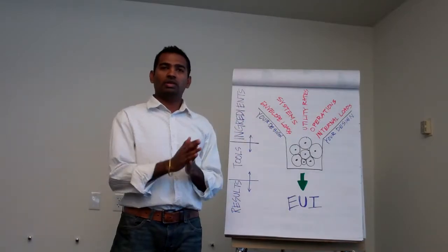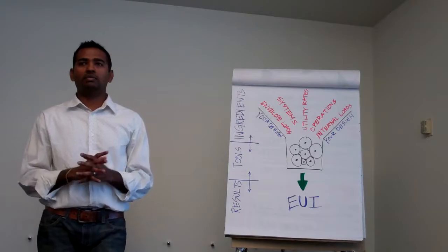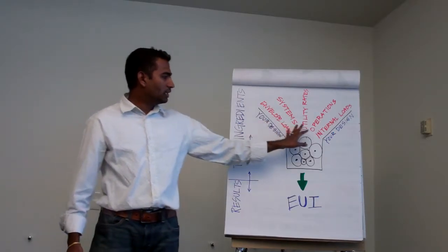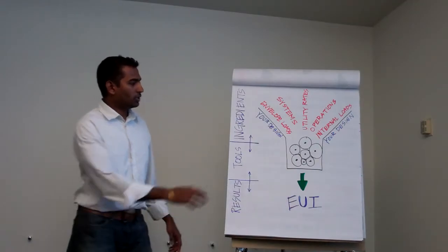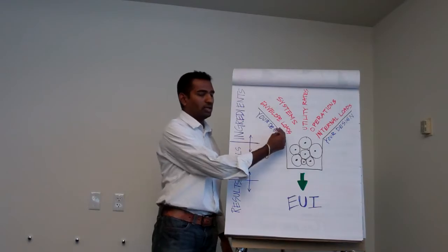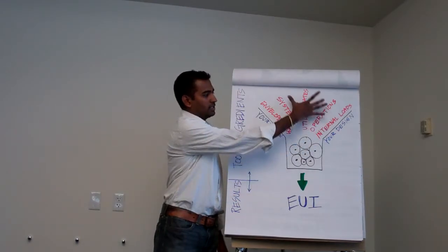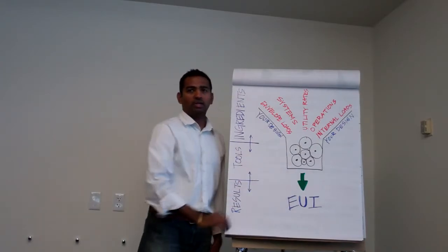Is it operated during the entire year, or is it only a 9-month school? So you need to know these 5 major items to figure out your EUI. And right now, there is no easy button, so the only way to find out what your EUI is, is to take all this information and use one of the tools to find your EUI.